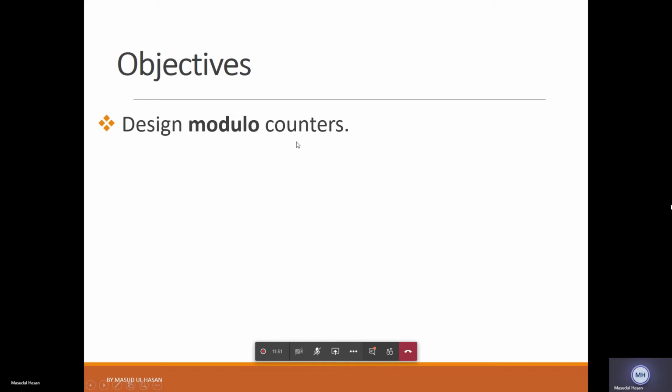But this thing will do what? You know that each circuit has some propagation delay. You have calculated the propagation delay of a full adder, if you remember, in experiment number 3. So due to this propagation delay, this clock will be at a different time than this clock. With this red line, you can see that there will be a small delay.